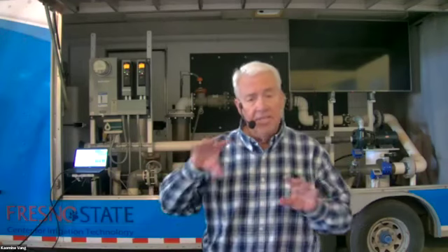About in the industry, are farmers expected to know how to program a VFD, or is that an installer job? No, normally it's installers. You have to set up the parameters your irrigation system requires, which I'm going to do an example of now, showing how they'll set up a certain discharge pressure that you want to meet all the time. Maybe you have multiple flows and pressures. They can set this up in the VFD under different programs.